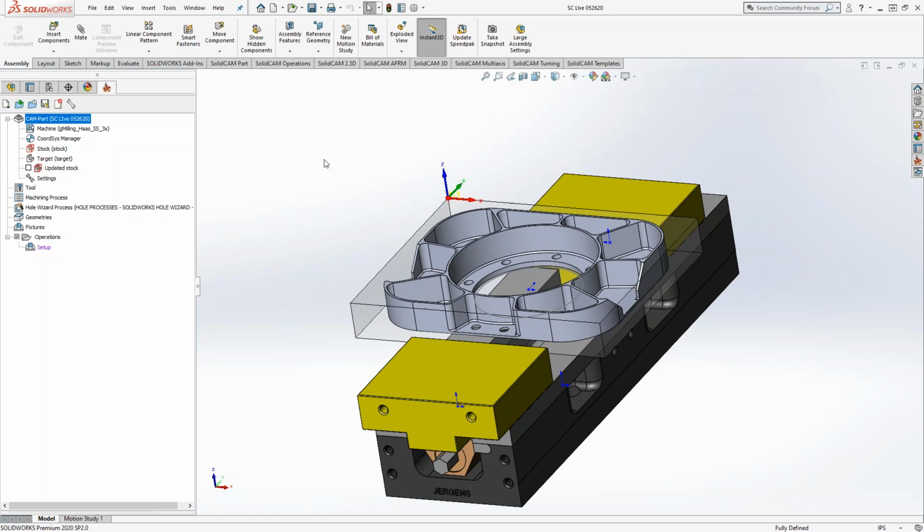But then, instead of putting the coordinate system in the top left, I would put it right in the center. The reason for that is maybe towards the front of my part we're right on size, but maybe my saw blade is getting dull on me or something like that. So we have a little bit of a draft. Well, by probing or putting that coordinate system in the center, it accommodates for any extra material in a way. So it's finding the exact center.